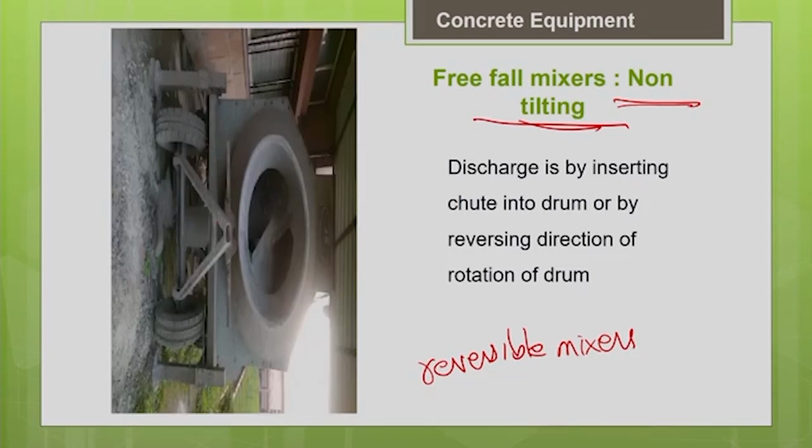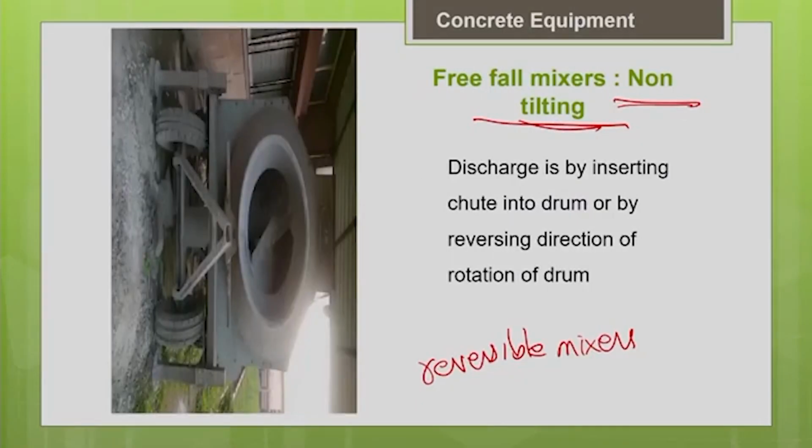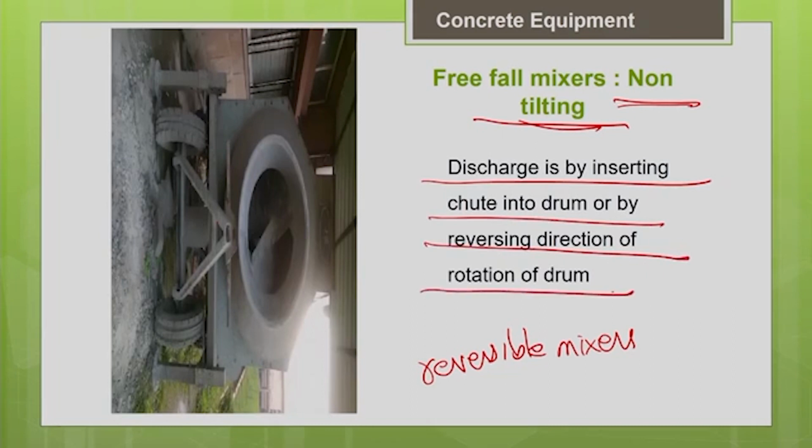So, by reversing the direction of rotation, I can discharge the concrete out in these non-tilting mixers. The discharge of concrete can be done by inserting the chute into the drum or by reversing the direction of the rotation of the drum.